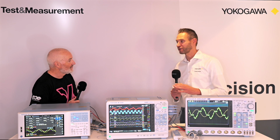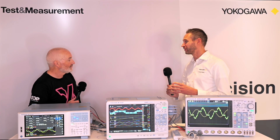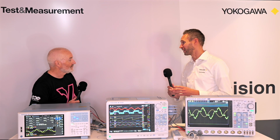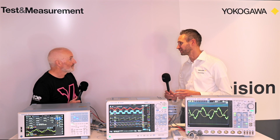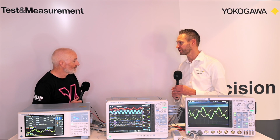Now, Michael, tell us reasons why you would choose a ScopeCorder over a power analyzer and/or an oscilloscope. So the ScopeCorder will offer the capability not only to measure the electrical signals like the other two instruments do, but it also offers the capability to measure at the same time physical parameters like strain, vibration, temperature, etc. And it can read data from communication buses.